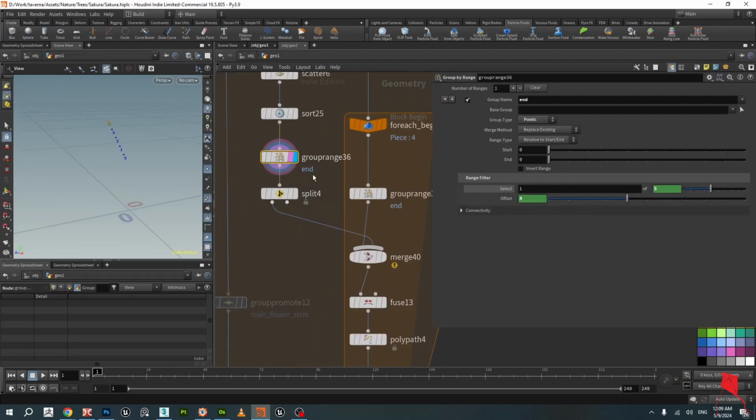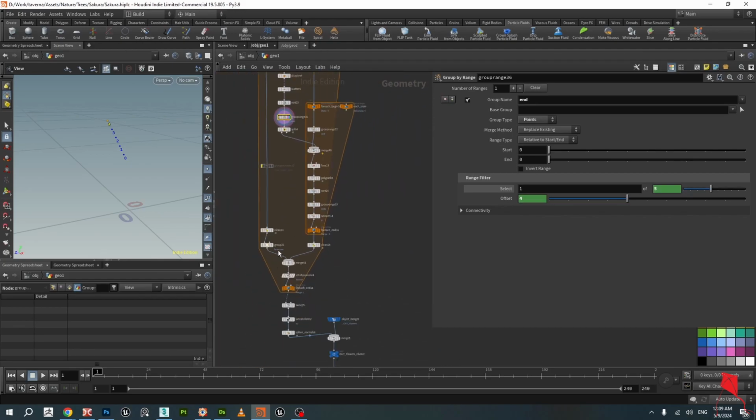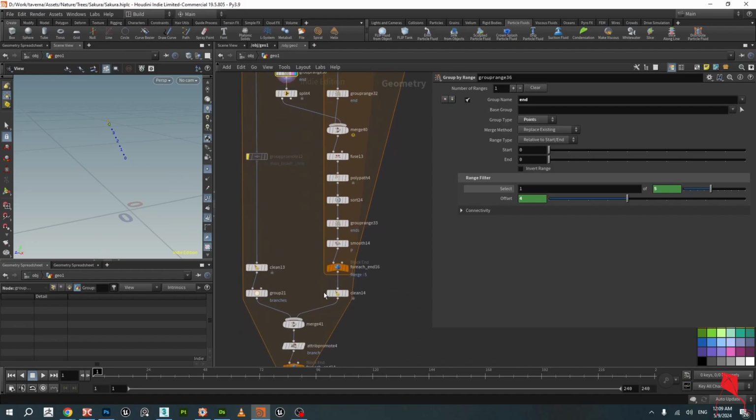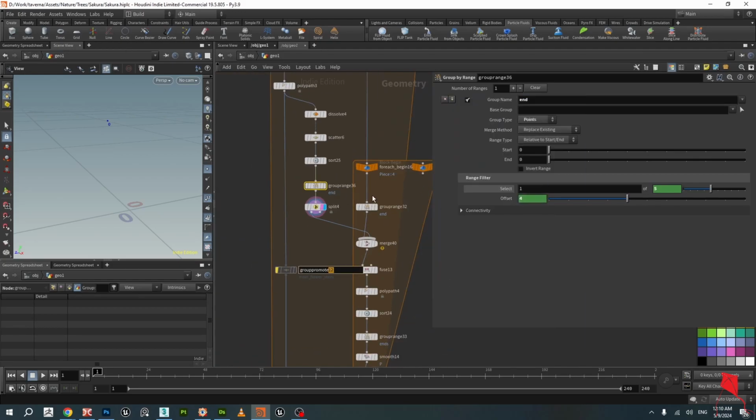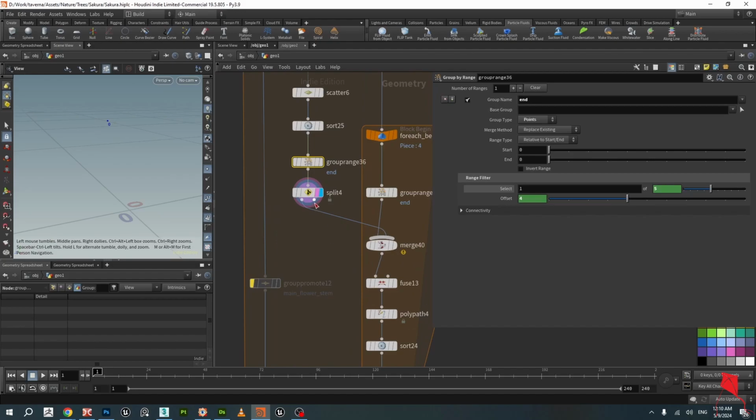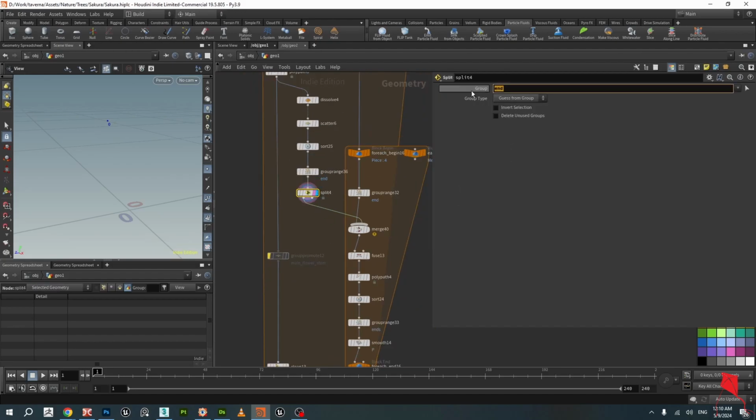So that's what we do. And while we do this in a cycle, every time we split this endpoint. Because we named this group endpoint, and on each iteration the endpoint is different. And so we split it. You could blast it here, just the same. So group end, that's it. Split or blast, it doesn't matter.